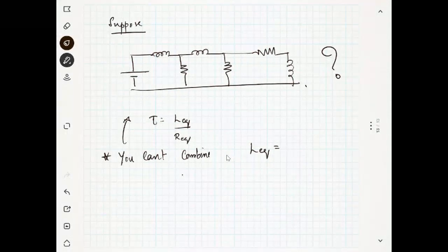Of course, some frequencies will come because of the exponential behavior, but it's not in the same way as we usually handle AC signals. For AC circuits we usually find the impedance, but for finding the time constant that will not work. Both are different logic. That is the problem. So in this kind of circuit, we have not only one time constant, we have multiple time constants.